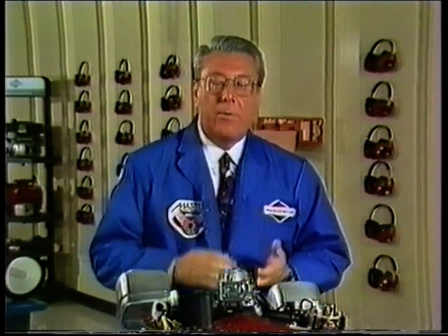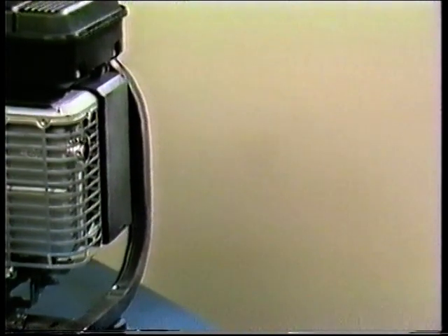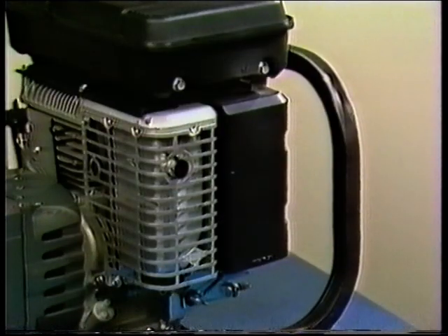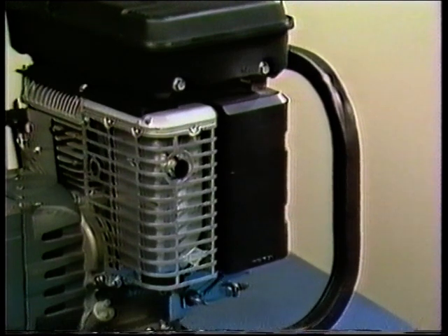The engine only performs poorly under load. Under load performance problems are almost exclusively caused by debris in the main jet, nozzle, or air bleeds. To determine where the debris is most likely to be, check the engine's exhaust. Black smoke results from an excess of fuel, indicating that the air bleed may be blocked. No smoke and no black residue on the muffler deflector indicates a lack of fuel, and most commonly an obstructed main jet.